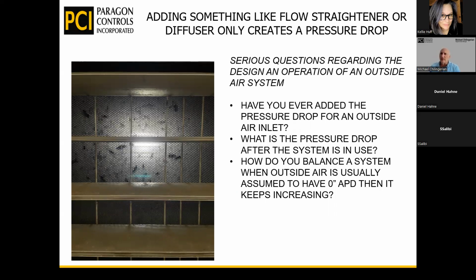There are issues with other ways of doing airflow measurement, and I was just out at a hospital over here in Sacramento, where they had an airflow straightener and diffuser plate that they were using for outside airflow, and this was something that they actually maintain on a regular basis. But you can see that this kind of stuff gets clogged up with particulates that are in the air on a regular basis. So there's a lot of things that you need to look out for when you're doing outside airflow measurement.